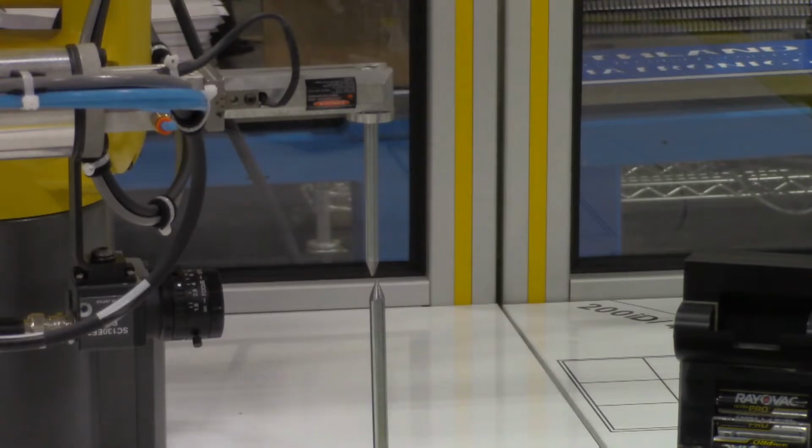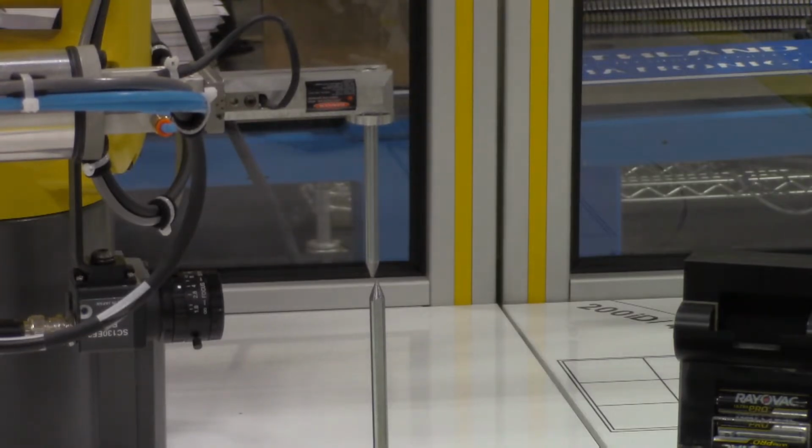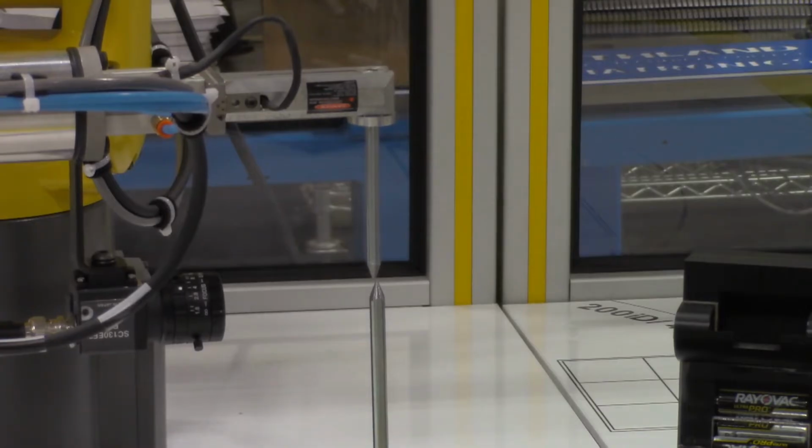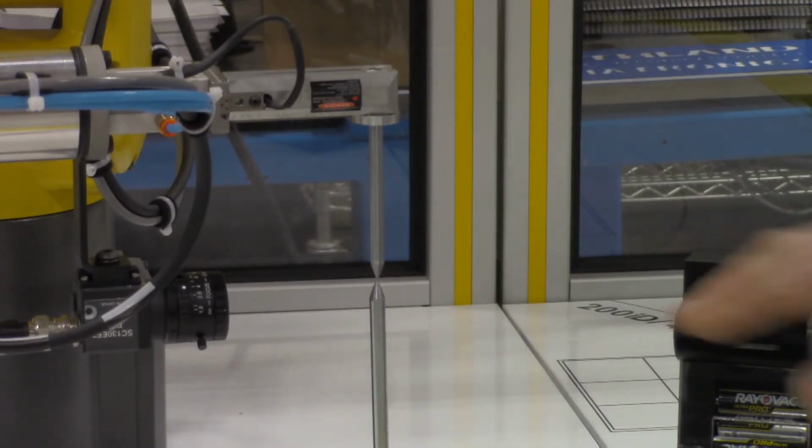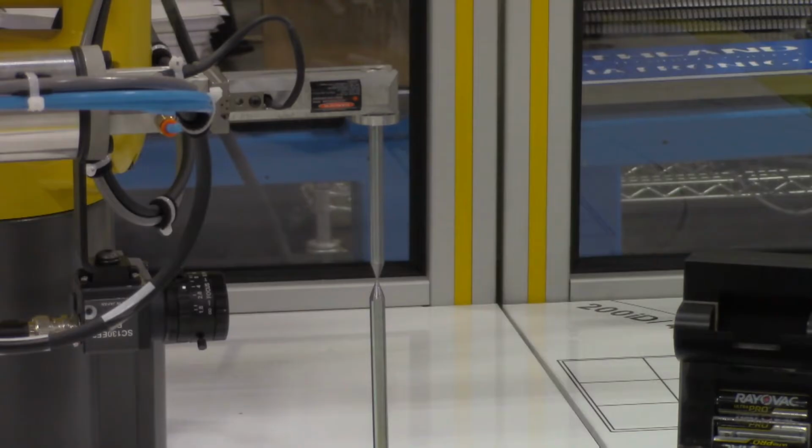And it looks like I can bring my z-axis down a bit. And what we're aiming to do is just get these two to pretty much be touching. Okay, I'm very happy with that. So I've got my first point of the 3-point method where these are basically touching one another, and we're going to go ahead and record that point.